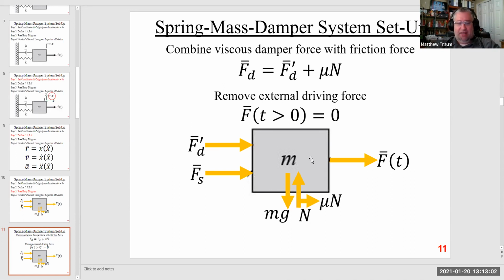If you didn't have that in there, think about driving a car. If you didn't have some sort of damper to damp out the oscillations and you drove your car over a speed bump, your car would just continue oscillating up and down basically forever. And it would become really uncomfortable and difficult to drive as the car sort of bounces up and down as a result of having driven over the speed bump with no energy dissipation. So the way that the dashpots actually work is that typically they're viscous fluid devices.